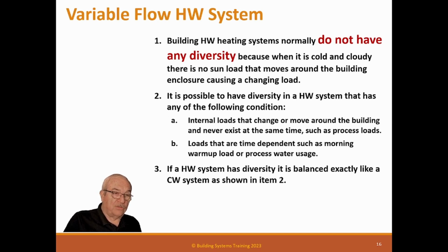And one thing about hot water systems that is good to check: does the pump flow match boiler flow? Does it match coil flow? That's how you'll tell, because I've seen jobs where the pumps don't match the boilers, the boilers don't match the coils, and the coils don't match either one of those, which means that was a design error, and that should be looked into by the designer.